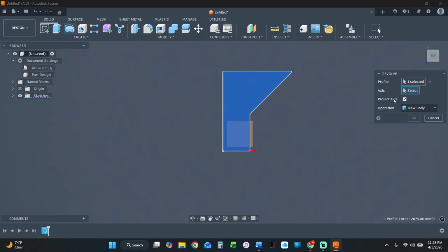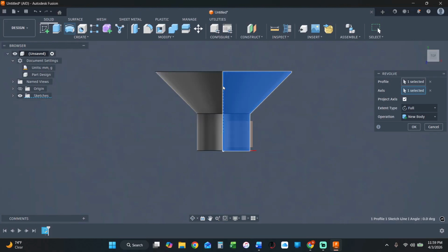Now once you're in your revolve, you have your profile selected. So that'll show it's the area enclosed by your sketch. And then the additional selection you'll make in revolve is going to be the axis around which you revolve the sketch. So in this case, we'll change this, and we'll kind of study what the impact is by changing that. But you'll select that axis.